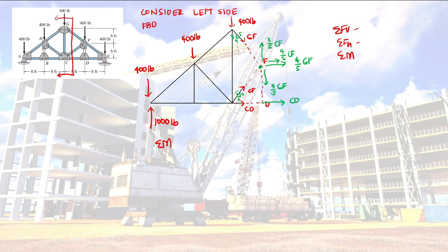In your summation of moment, mas magandang hanapin mo kung saan yung joint yung may pinakamarami na forces. Now, in this case, ang pinakamarami na forces ko is yung F. So, doon ako magmo-moment. 0, clockwise positive. Bakit dyan? Because pag dito, these four forces would not rotate. So, ano lang yung mag-rotate? Yung CD. Then, the forces and the reaction. Masasolve ko na agad yung CD.